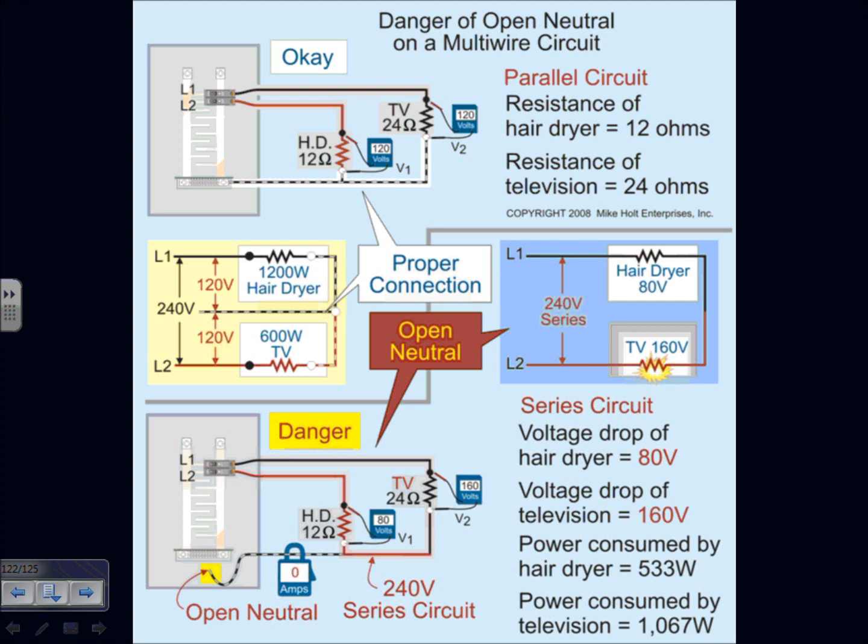I put ground to ground. The second thing I want to do is what? Your 3 wires: you're going to unscrew the wire nuts and put 1 wire underneath it, right? Good for the ground, no problem. For the neutral, there's a bunch of white wires under 1 wire nut. I unscrewed that wire nut, not knowing, and I should have known, that it's a multi-wire branch circuit. The minute I unscrewed it, they went open.